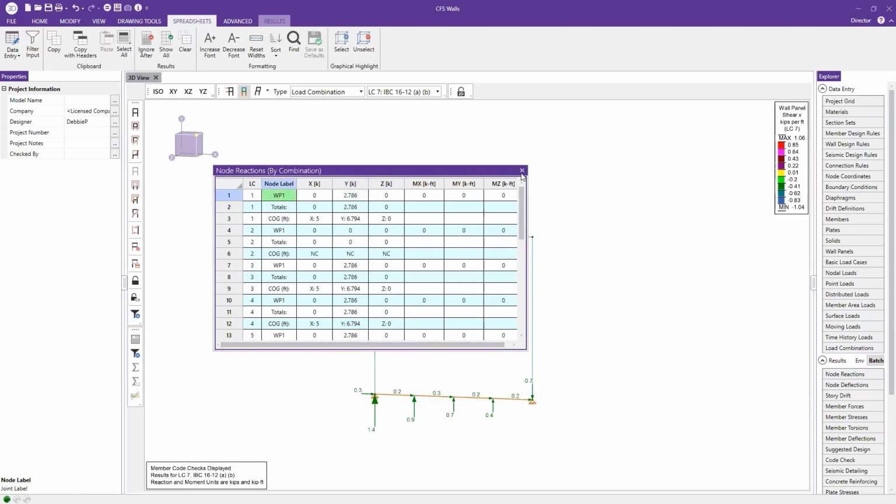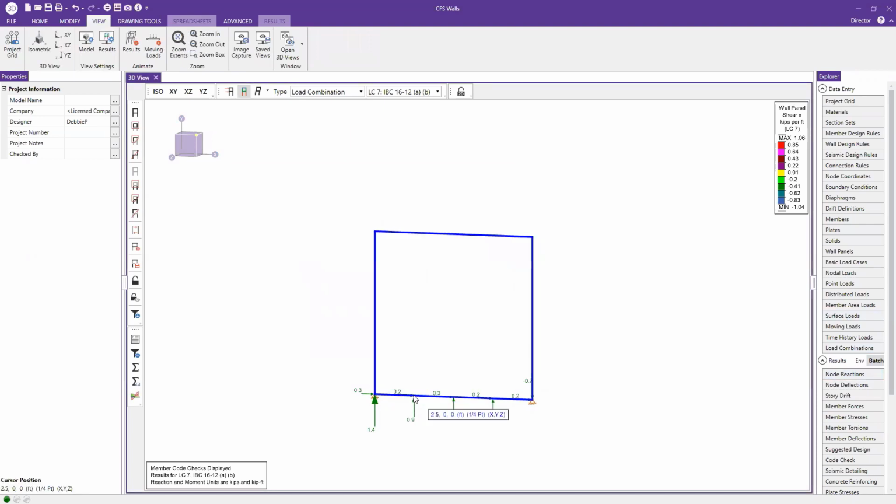But it's always nice to understand what's happening along the way internally. Those plates are breaking it up into pieces, and each one of those corner forces is tied down as either a pin or a fixed boundary condition. So it's a nice way to understand, for this load combination, how the forces are distributing along that boundary condition.